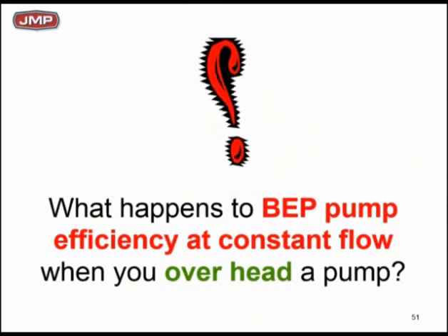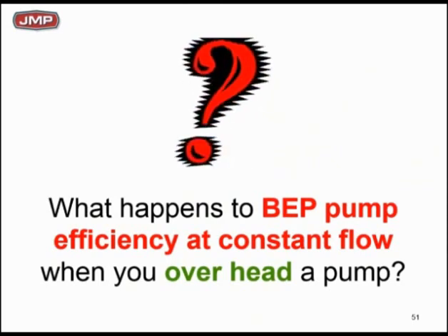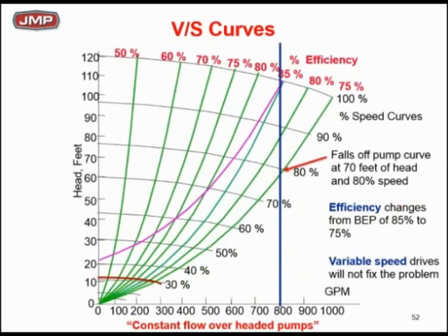We'll see some of these same slides, just trying to make a point to you. We're seeing this issue in lots of places. I've seen it in Chicago, I've seen it in Raleigh, I've seen it in LA, I've seen it all over the country, because people are buying pumps and just thinking they can put a variable speed drive on it and fix all their problems. You cannot. You cannot do that, and this is where we're getting in trouble. So let's get across what we're saying here.